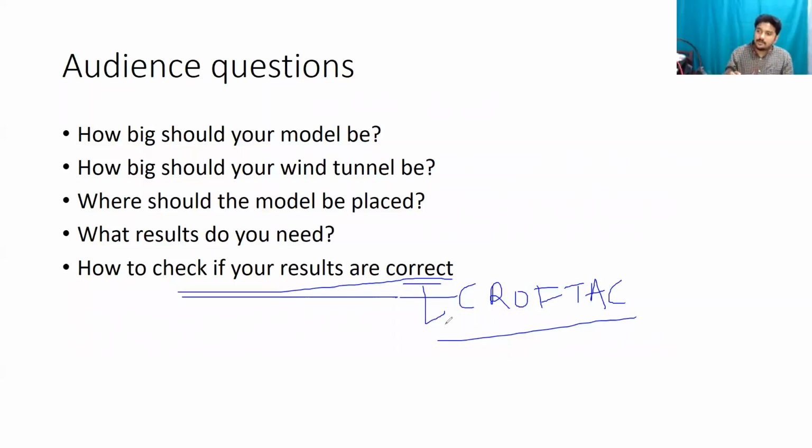On a scale of 1 to 10, please rate your understanding on this topic, like how to perform validation. All right, perfect. That's what I want to see. So remember, next time when someone is giving you, when you have an object on which you have to do CFD analysis, always try to validate on a different system for which data already exists.